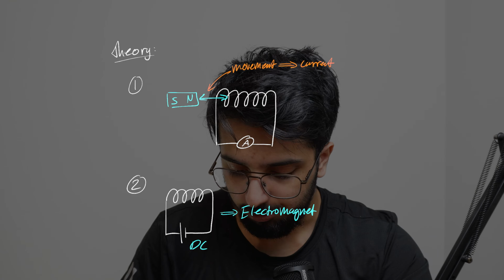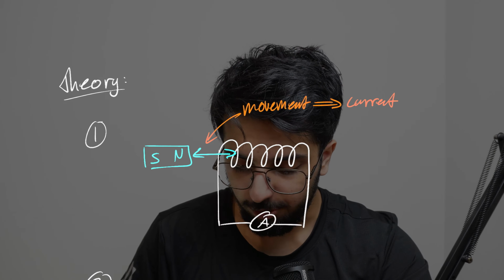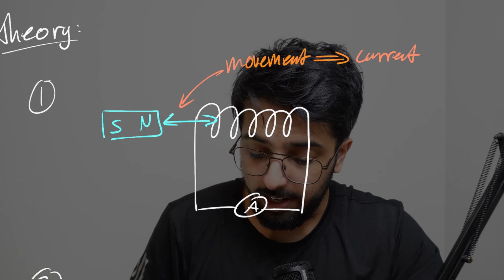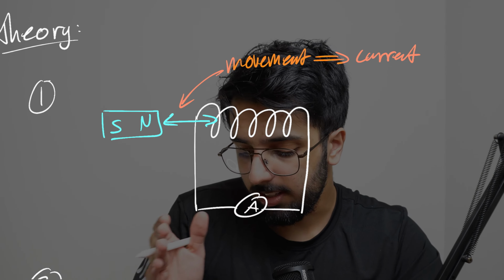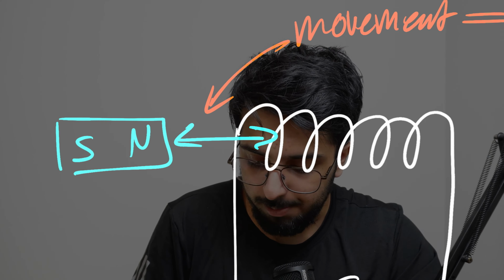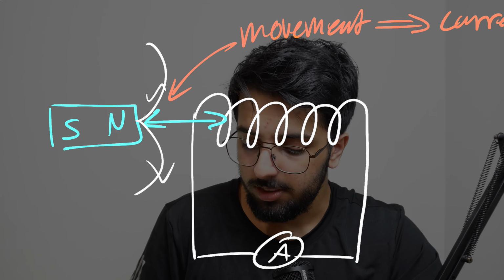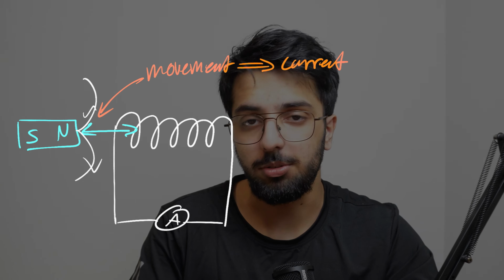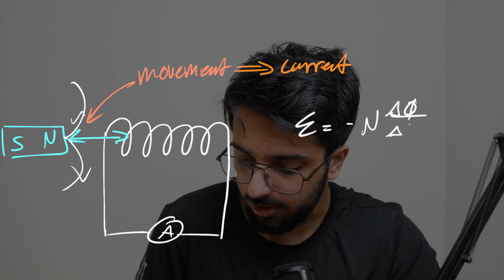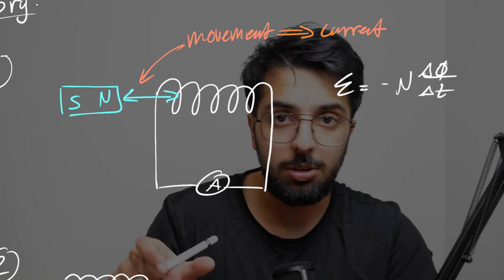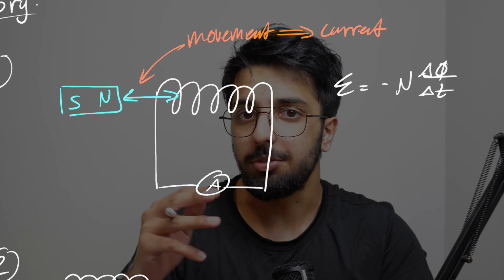First we're going to go through 4 pieces of theory about how electromagnetism works. The first is about inducing an EMF. We have a bar magnet, and we can pull it in and out of the coil. This bar magnet has flux lines, and as these flux lines interact with our coil, there is an induced EMF, an induced voltage, and therefore an induced current, due to Faraday's law. As we continuously pull the bar magnet in and out, the induced EMF and current flip directions constantly.